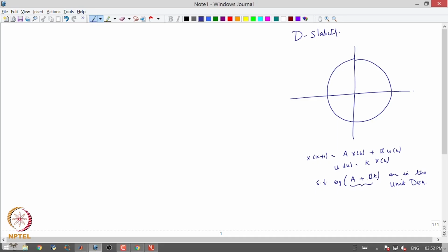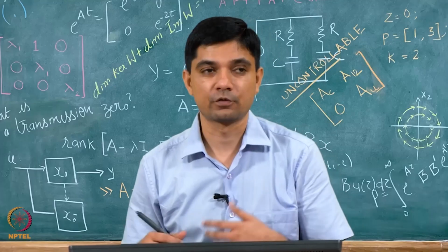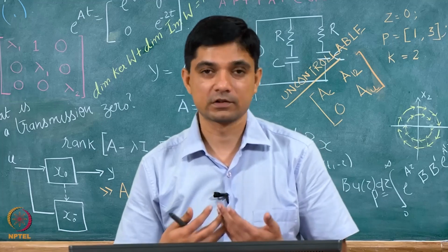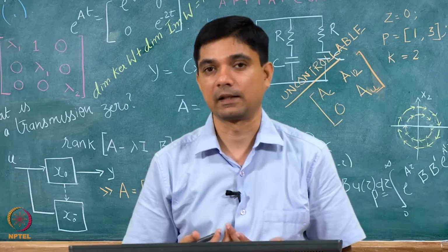And we now know how to first formulate this as an LMI. That is what we learned in lecture number 1. Again, I am just dropping the minus K here, which we would usually use, but nothing really changes. Usually I am not only looking at stability. In addition to stability, I am also interested in performance, and performance usually translates to placing poles of my closed loop systems at appropriate locations.